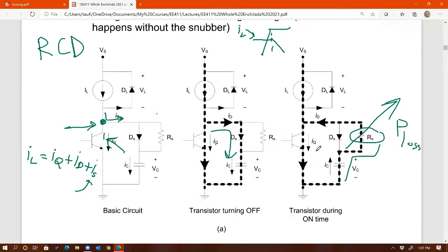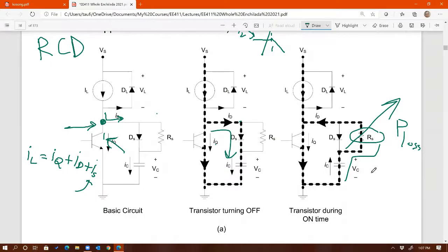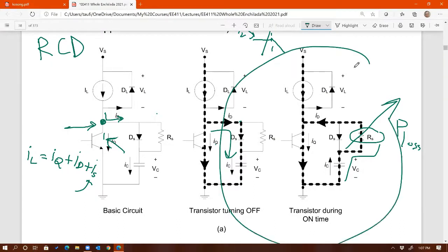Remember I said earlier about being careful when sizing these numbers? If you're not careful, even though the switching loss is minimized, the entire converter loss could be higher if you're not careful on sizing this capacitance. You see the problem there, hopefully.